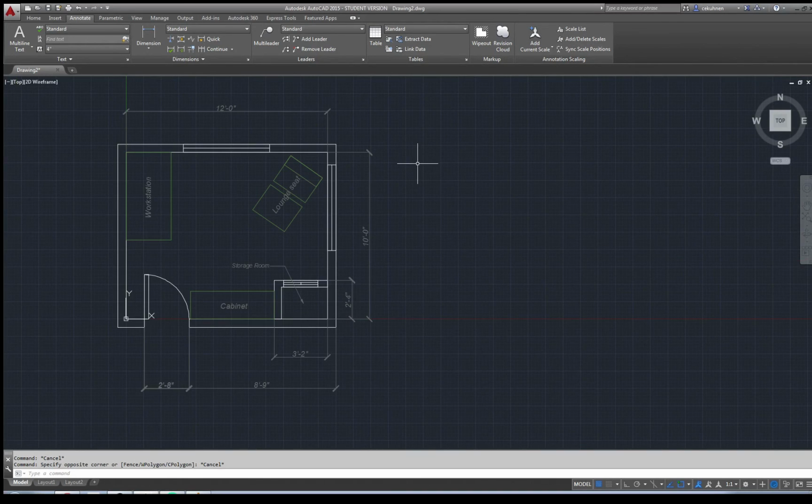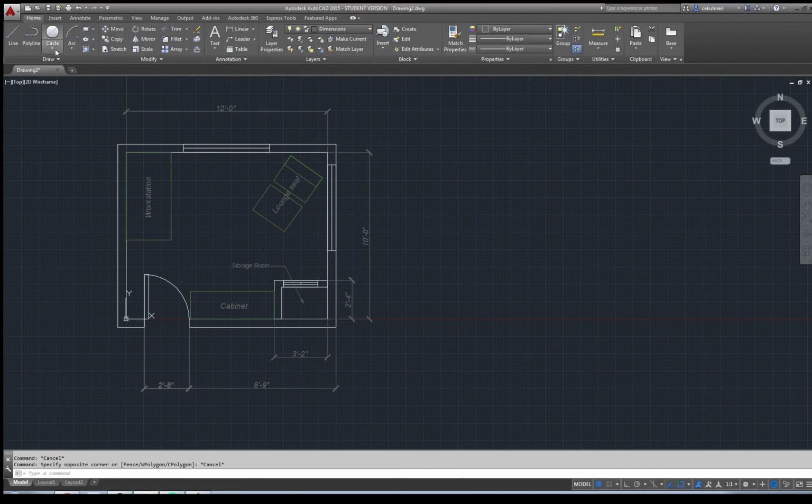Okay, I think this actually would conclude everything about the two-dimensional elements, giving you a rundown into how to use the styles, for example, for the annotations, for text, the leader, how, for example, to use some of the drawing tools, how to use the layers and the property tool, the group tool, the ungroup, and in general, like some of the ideas how to plan ahead and create your design structured onto different levels.